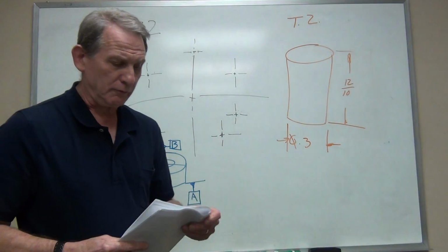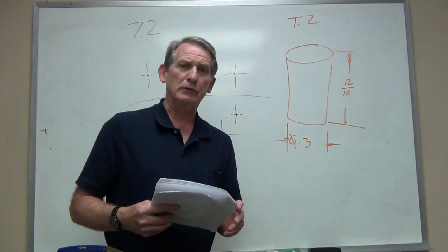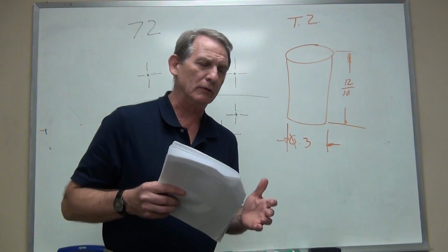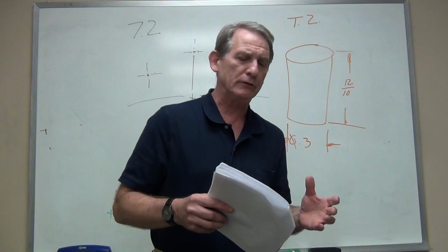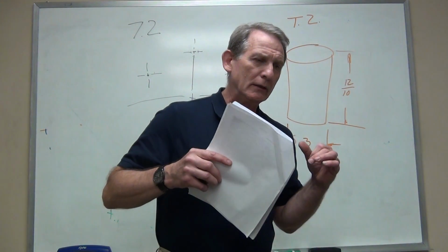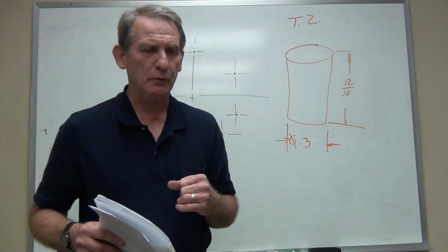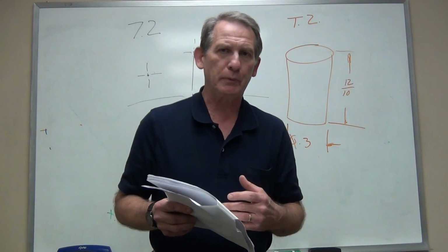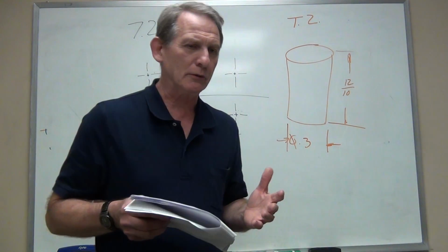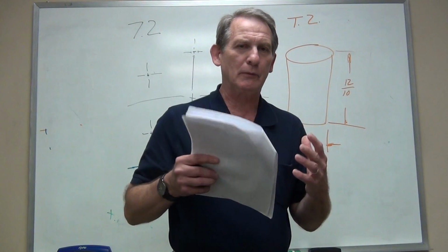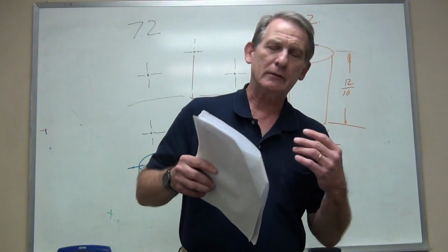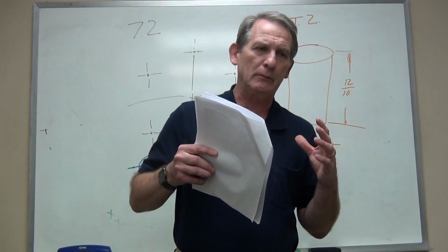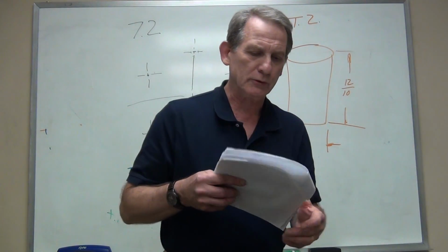Okay guys, this is the second video of position and positional controls, and again this is a big chapter, and again I'm not going to even try to get through all the variations and ways we can manipulate this system to control. What I really want to focus on is the fundamentals of position, and the fundamentals of position rely on at least some fundamental understanding of datums and the tolerance zone and basic dimensions and all those things. They come into play very strongly with position.